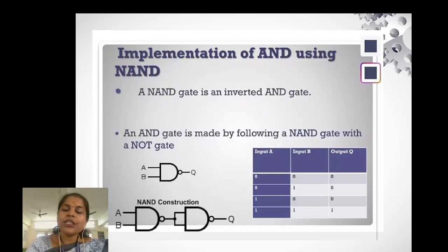And this slide shows implementation of AND gate using NAND gate. Let us implement an AND gate using NAND gates. A NAND gate gives the output (AB) the whole bar. However, we need AB. To obtain AB, we can pass the NAND gate output through another NAND gate configured as a NOT gate. Mathematically, you can say this as AB equals ((AB) bar) the whole bar. So the first NAND gate generates the complement and the second NAND gate removes the complement.